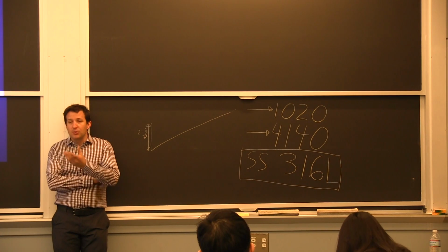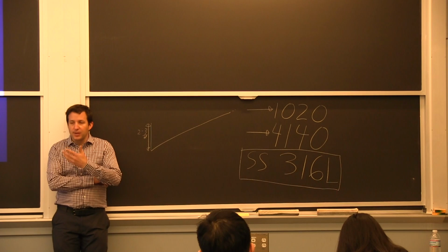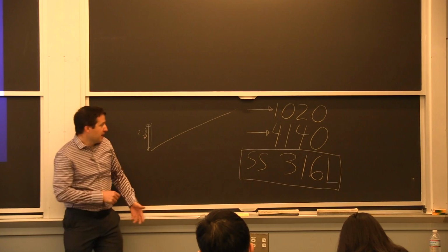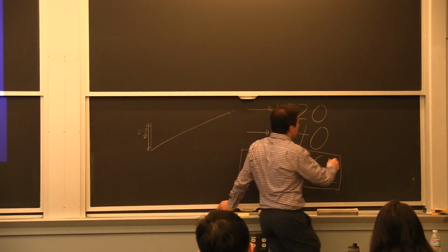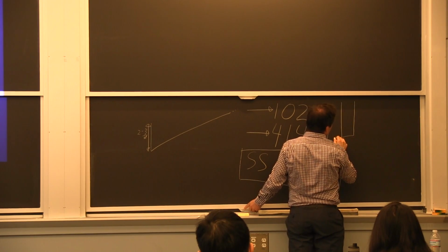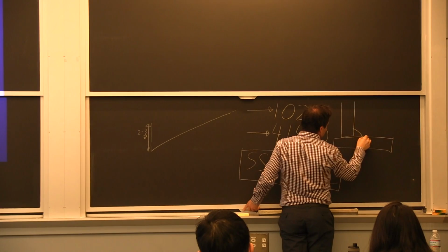It's not so much in the weld pool, because a lot of times you can come in with a filler metal that has so much chrome and nickel that it will be corrosion resistant. What matters is the metal that's in the heat affected zone right next to it. So if I have a fillet weld here, and I just do a single bead,